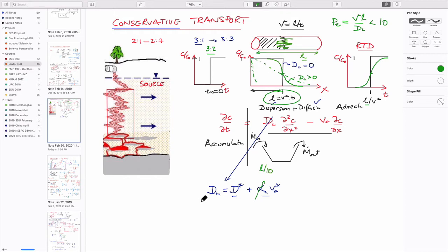But field experiments, where you look at how the plume grows by taking snapshots at a variety of different times, allow you to come out with a field estimated value of this dispersion coefficient, which you can then use in forward models to look at where the plume might be in another year or 10 years if you do nothing, and to design a remediation plan to do something about that. So that was kind of what we dealt with in those 3 classes.